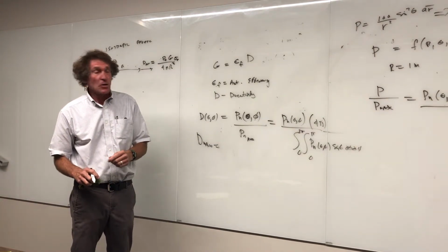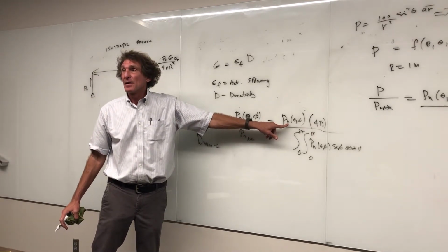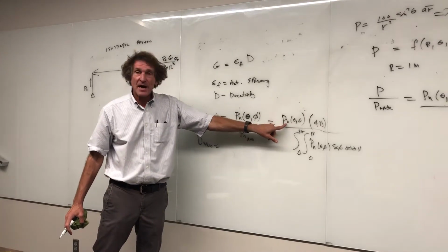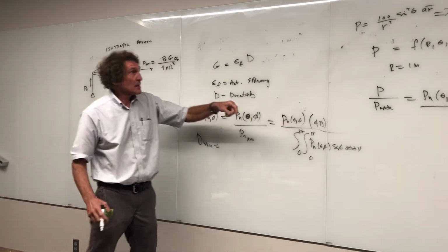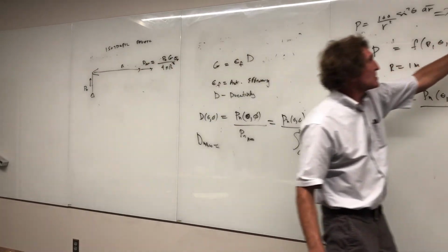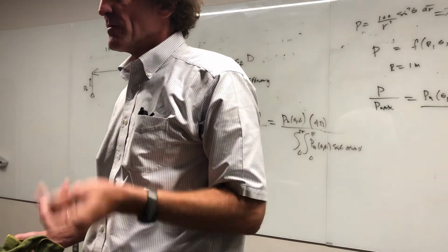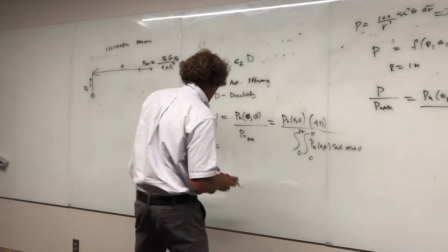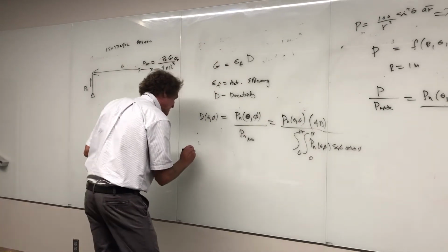All right, look here. What's the maximum value of the normalized power? The operative word is normalized. 1. Are you with me? So the maximum value this can have is 1. That P normalized of theta and phi. Think of this: remember how I said this sine squared of theta was the normalized power density? Well, what's the maximum value you can have? 1, right? Just 1. All right. Well, the maximum value, D max, right here, would just be when that's 1, so just put this down.